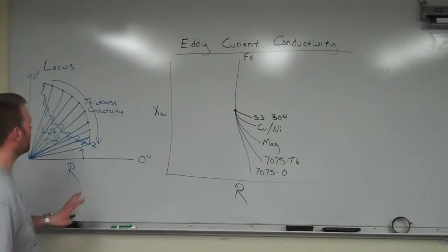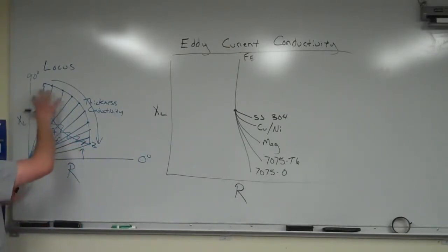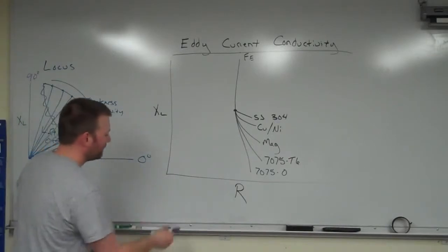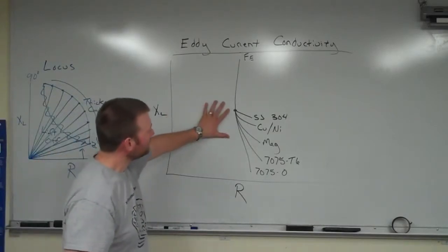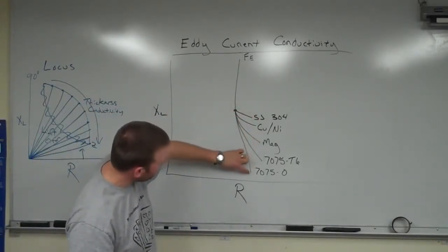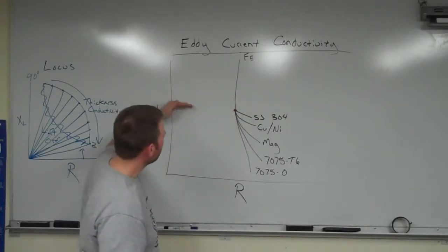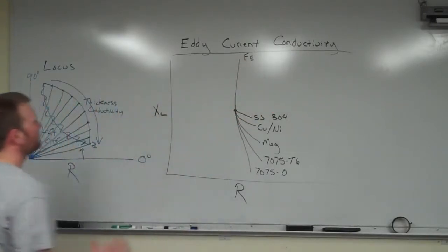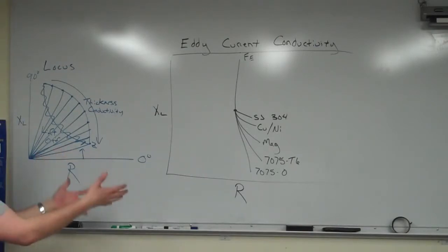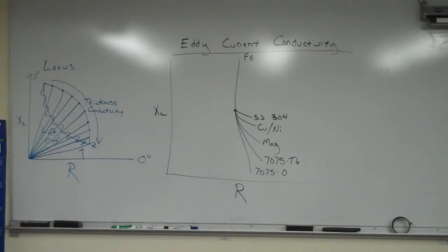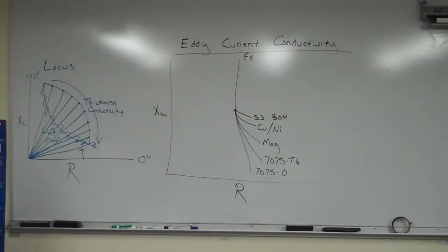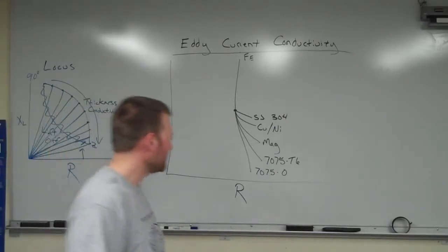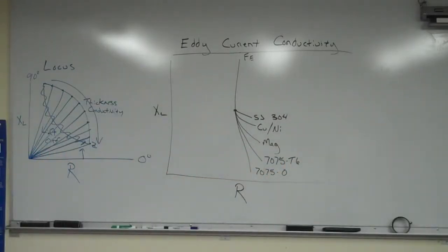Now, what we're more concerned with for now is just our conductivity lines and how this all plays into measuring the thickness of a piece or measuring different materials. So, a basic conductivity curve has increasing conductivity as we come down here, and ferrite or anything magnetic falls up here, which is how I orient my screens. You don't have to orient yours that way, but it's easier for me to understand: with inductive reactance and resistance, if it's magnetic, everything goes up, and if it's non-magnetic, everything comes down. So that gives you a little shot of what's going on there.